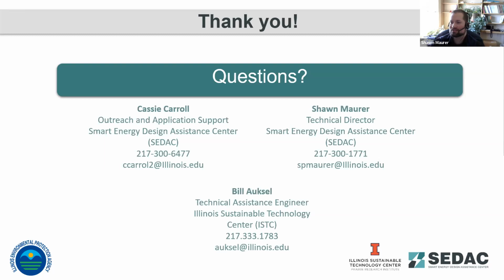Yeah, I know on the energy side, when we look at lift stations, we're looking at, is there turn down capability and energy savings versus an on-off control for a lift station. And usually what we're looking at in energy savings is if you can put a VFD in there, we've seen some systems do a constant level for that lift station, as long as it's meeting that minimum flow requirement through the piping to prevent settling.